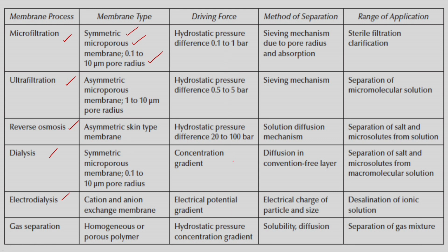And the driving force. Everywhere it is the hydrostatic pressure; in dialysis it is a concentration gradient; in electrodialysis it is an electrical potential gradient, right. And the method of separation: sieving mechanism due to pore radius and adsorption in microfiltration, we already told because of the protein concentration; the sieving mechanism in ultrafiltration; solution diffusion mechanism in reverse osmosis; diffusion in a convection-free layer in dialysis; and electric charge of the particle and size in the case of electrodialysis.